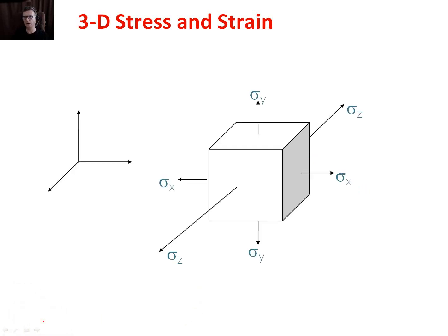We're not going to look at 3D stress equations, but it's quite straightforward to extend the 2D example we've just given onto 3D. That's not a big deal. So for example, if you were looking at how we'd expect something to change in the x direction, we would expect that if I apply stress in the x direction divided by the Young's modulus, it's going to get bigger. Then if I try and squash it, I need to put a negative sign there.